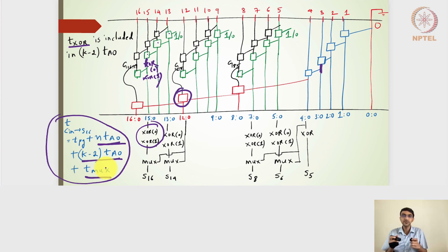So in this particular lecture, what we had seen is we started with the carry increment adder, and then we looked into the carry select adder. The carry select adder requires a lot of hardware. We assume that the carry input for a particular group will be 1 and 0, and then compute the sum bits. So it will require a lot of parallel AND OR gates, and then it is going to generate the pair of sum bits, which will be going into the multiplexer groups. The multiplexer will get a select line, which is generated from the carry out of the previous group. So based on the carry out of the previous group, we will have the real sum bits extracted.